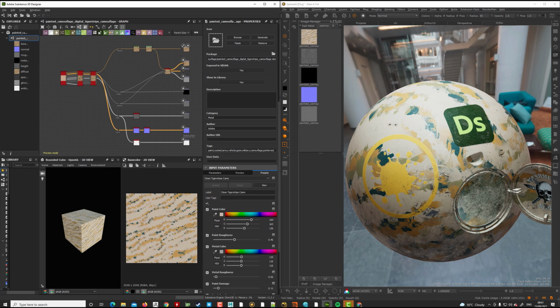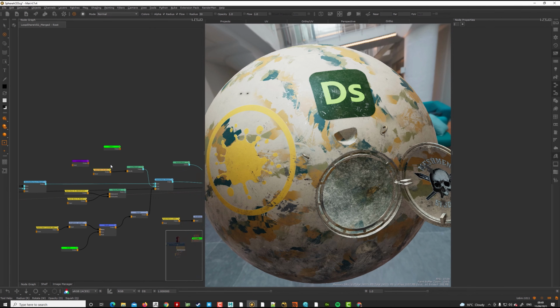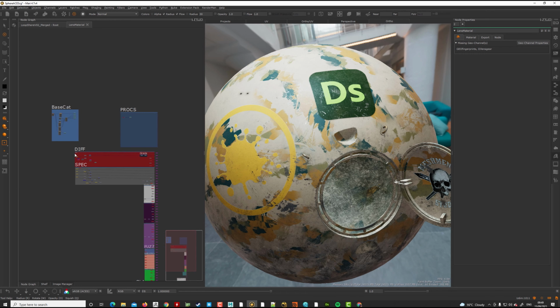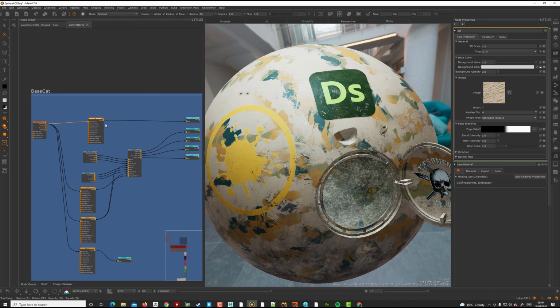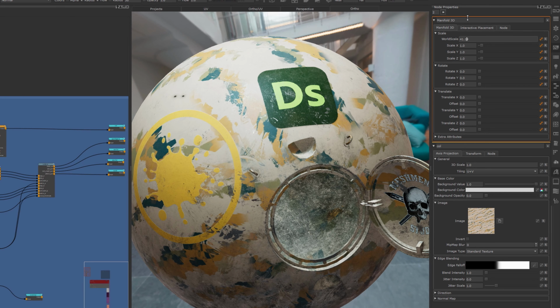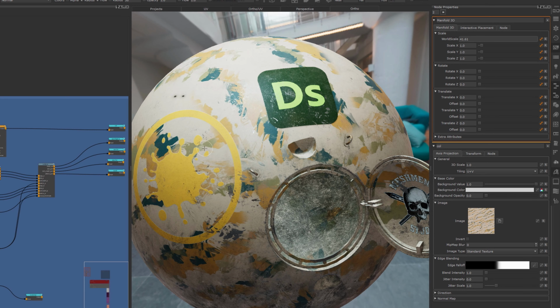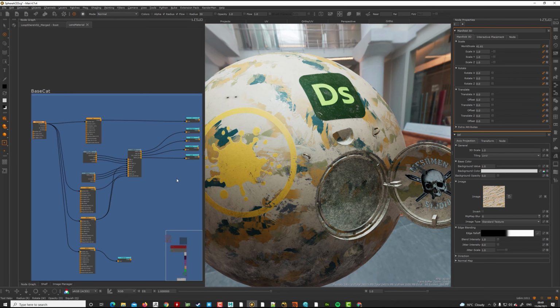This is a Pixar surface material, as this one is using Metalness and this one is using physical spec. I made a few bits and bobs inside the material to get that to work. The node graph is quite basic. Essentially this is the material, and I actually have some decals coming in on top. But let's take a look inside and see what I do. We have a few axis projection nodes, which is kind of like a triplanar projection. So if I tweak my world scale, this material will be applied with different scales. That's one part of the ingredient mentioned.